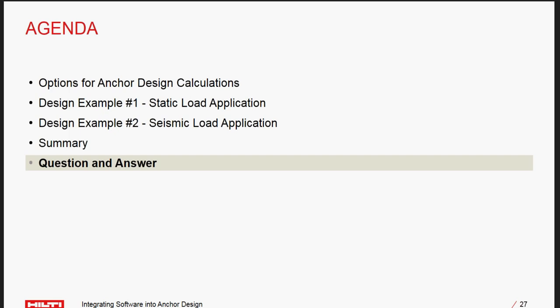So you'll see right here that the one I selected does not work, but there are some other ones that do. So I want to look into using RE500V3, that epoxy adhesive, and I want to use the 7/8 B7, which is that high strength threaded rod. To make that change in the design, all I have to do is click on the one that I want that's fully highlighted green across the row, and it's going to input that and use that for the design.